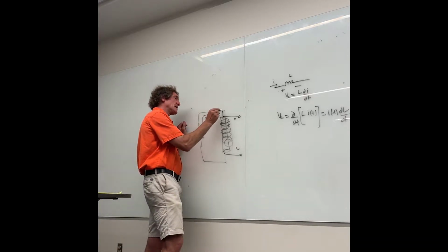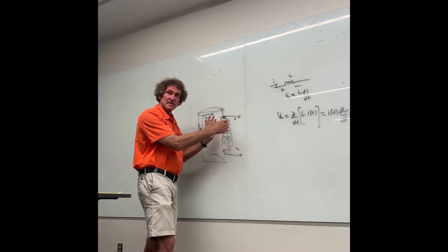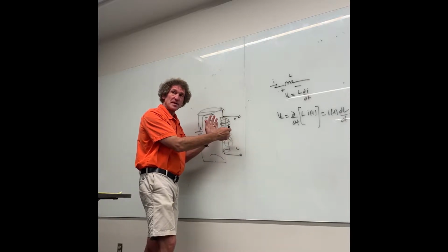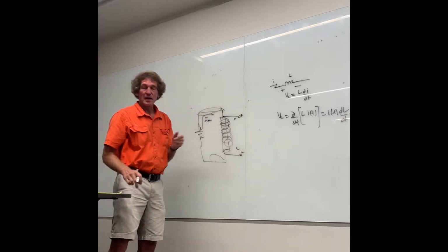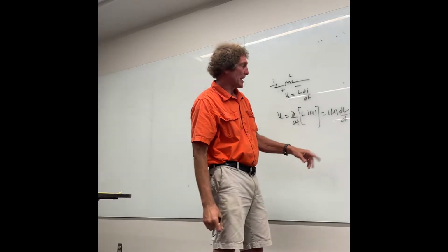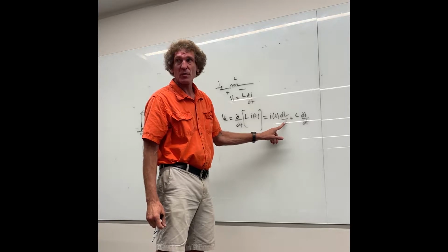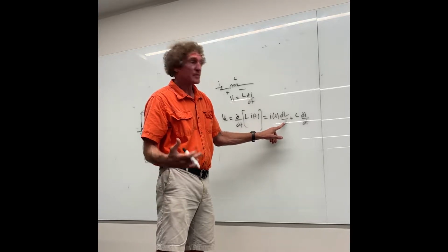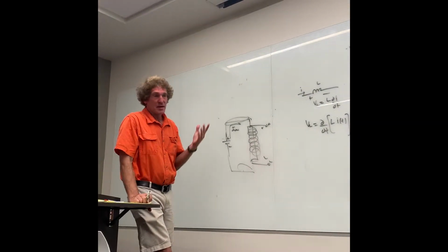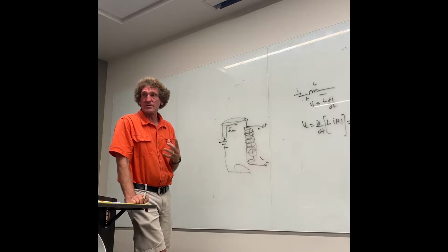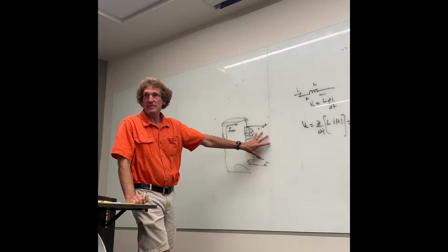And they also instantly blow out this line and this line. Now, what happens is you get a time rate of change of the inductance, but the current's still flowing. So in the initial picoseconds, the voltage here can get, if the current's a couple hundred amps, but this di/dt is 10 or 12 orders of magnitude in terms of the actual value compared to this, would be dominant, and they can get voltages of up to 1 billion volts, all right? Only for an instant.